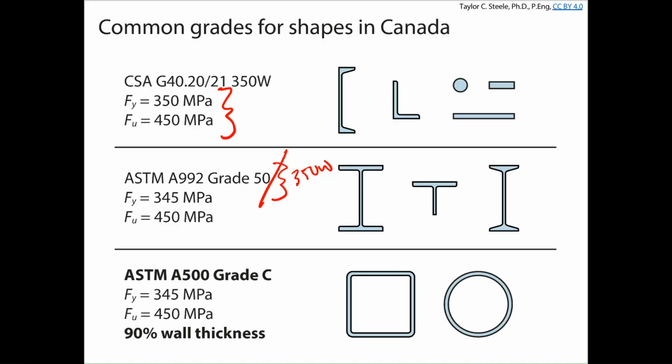Does anyone remember what annealing is? We talked about it in material science. Anyone remember the annealing process and what that does to steels or metals? Is that when you bring a steel or a metal to a heated temperature to relieve the stress, and then you allow it to cool off slowly?